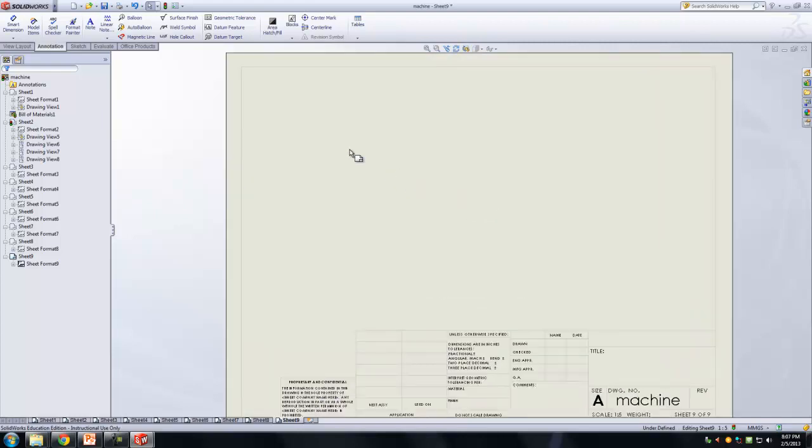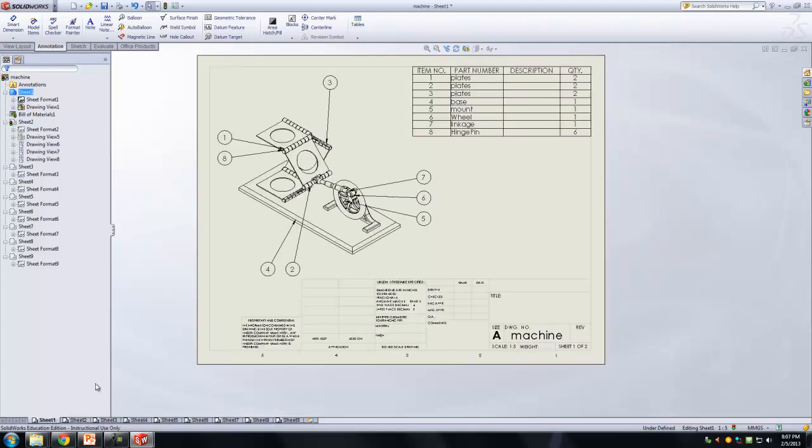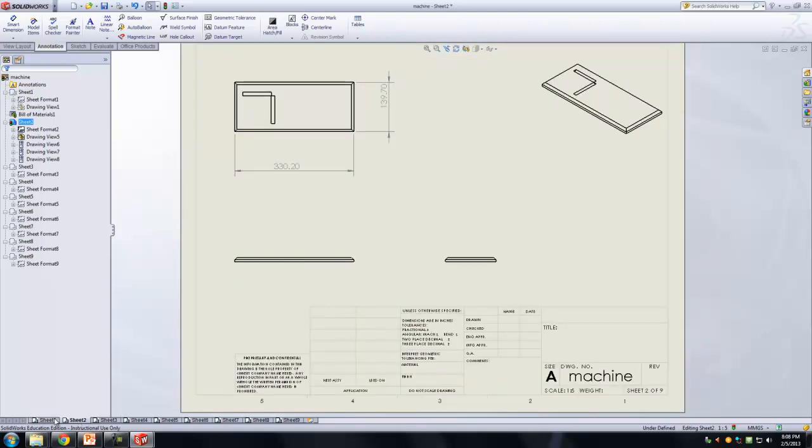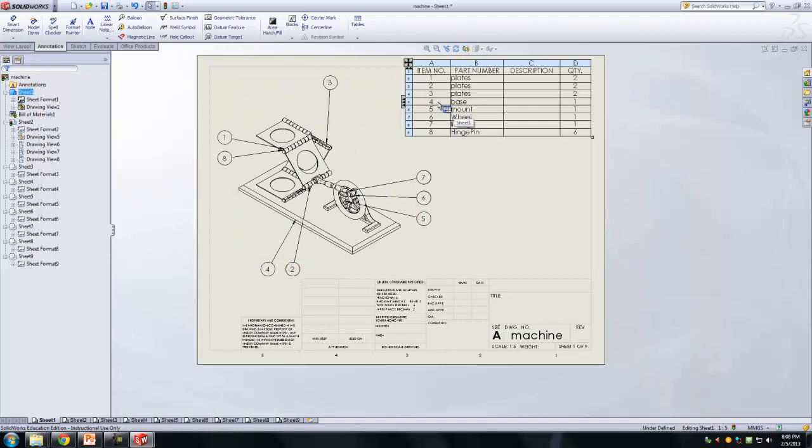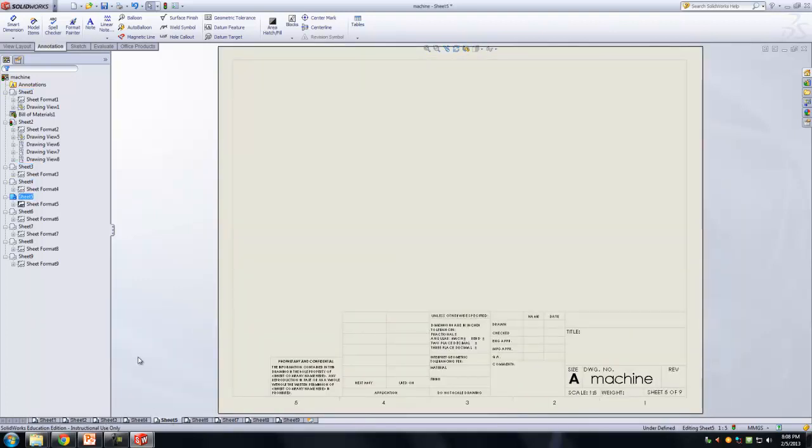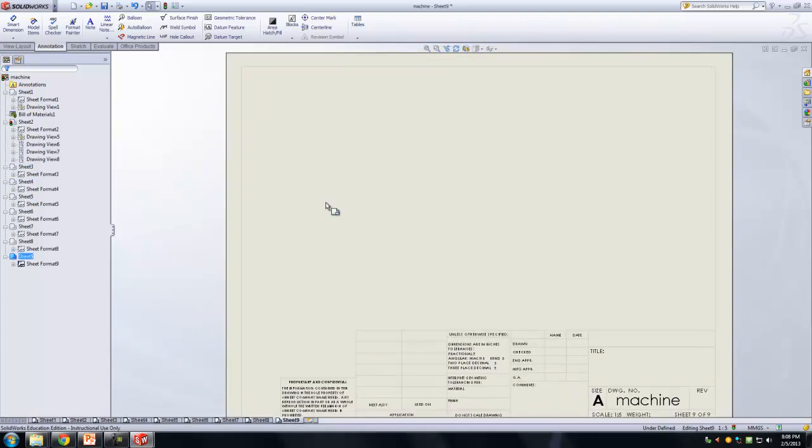It's very easy. You see where it says balloon over here? So if I come back to sheet number 1, this hinge pin is balloon number 8. And remember, I brought in this base as the first one, and that's a mistake because the base is actually the 4th one. So please make sure that you follow those numbers based on the BOM. So the second sheet would be part 1, part 2, part 3, part 4, and so on. So how do I create this standard part?